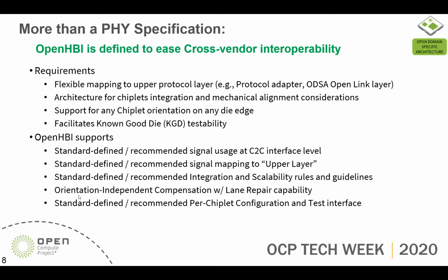The orientation independent compensation is a feature that we support in order to enable, if you have a misorientation, and we have a slide that talks about that, that we will still have this compensation to allow completely seamless and straight connections on the interposer, while the lane repair capabilities are maintained. So lastly, we also have a standard defined and recommended chiplet configuration and test interface, which will help to facilitate non-good die testability.